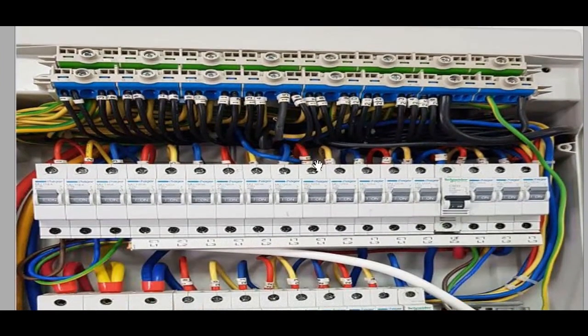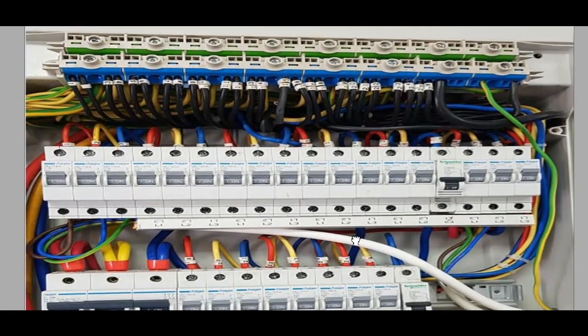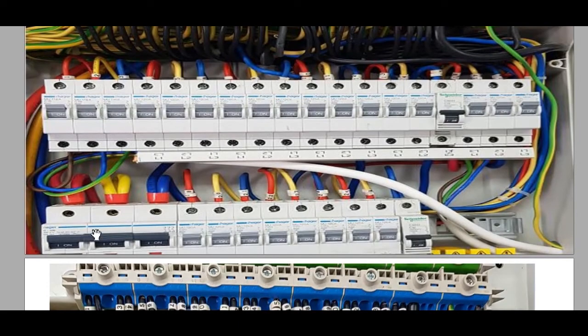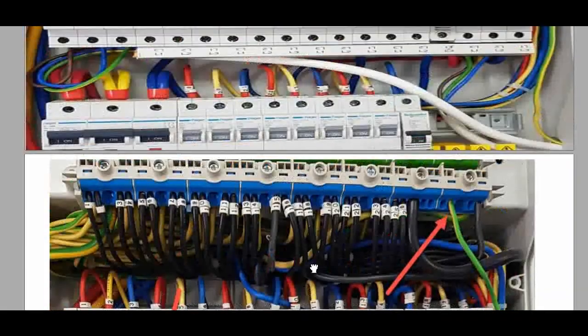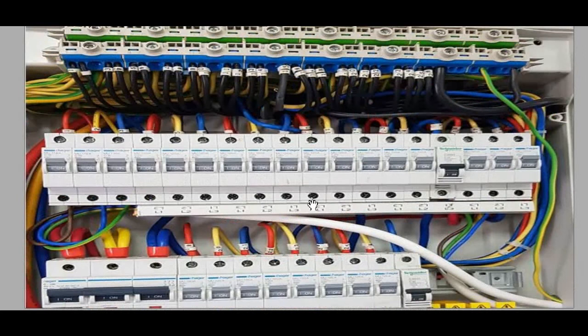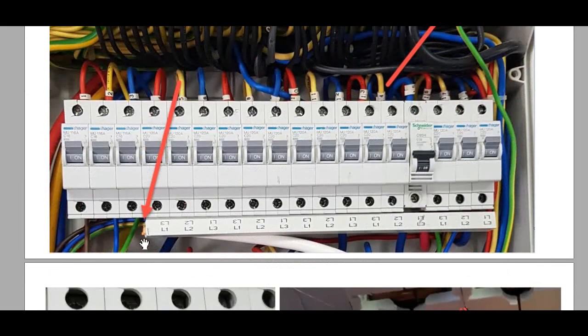As you see here, this is a panel that I inspected before. We have a numbering. We don't have RCD here either. Okay, we have a big problem here. Why? Because this electrician came and installed this bus bar, cutting it in an unprofessional way. He must cut it professionally and it must be isolated, not make the bus bar like this. As you see here, this is very dangerous because this is the line conductor bus bar. So you must isolate it and not cut it like this.